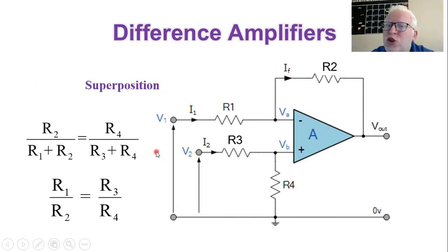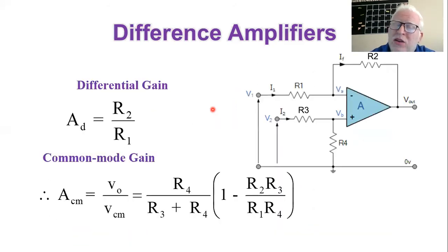We also showed the condition at which we can reduce the common mode gain to zero and maximize the differential gain to be R2 over R1.